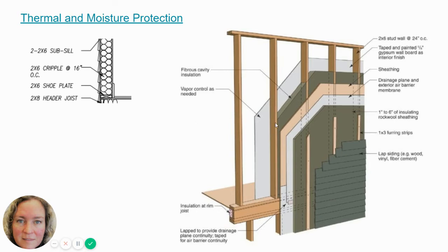And we'll see that everywhere we have a stud, basically think of that as a great conductor of cold from the outside, and that's where this extra layer of insulation is helping, because it's preventing that stud from getting cold from the outside and bringing that cold in. Older homes, if you've ever seen infrared studies done for older homes, you can actually see the studs.